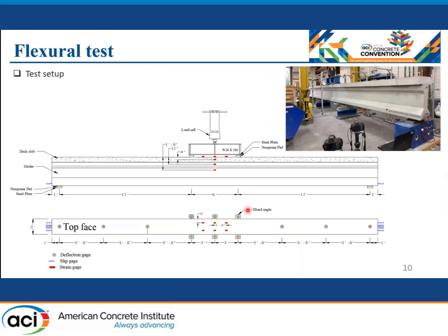Flexural tests. Here's the test setup. We tested the girders in 4-point bending. This is one of the girders before being tested. We did the test at the FDOT Structures Research Center in Tallahassee, Florida.